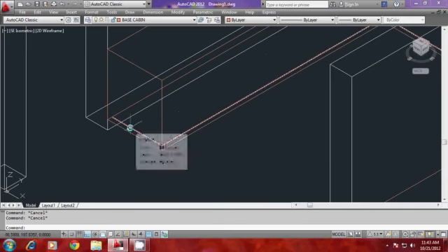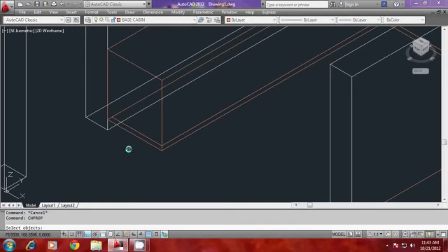The best method to give a thickness for the skirting is using a command called change property, because you know change property command will let you generate a surface out of a profile. So I give change property, and I've selected the profile. Then it will ask you which property to change. I'll select thickness here, so I'll give thickness. So it will ask you for the thickness. Thickness is -10, because it has to be given in the negative as a direction.